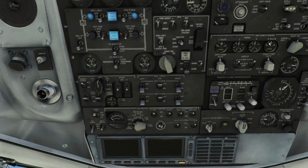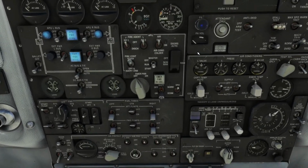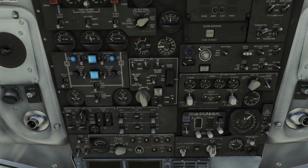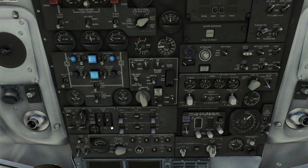So now the other part of the pressures, it's kind of scattered in a few places. This is where this can get kind of frustrating, but there's a reason for it. So you have an air switch here, you have air conditioning and pressurization over here, and then you have the mixed manifold pressure, the pneumatic pressure, right over here. And you think, what in the name? Why would it be over here? Well, because this is where you're going to reference it to make sure you have enough air for starting, which is where the start switches are. So it does make sense, but it's kind of odd that it's kind of moved all over the place.